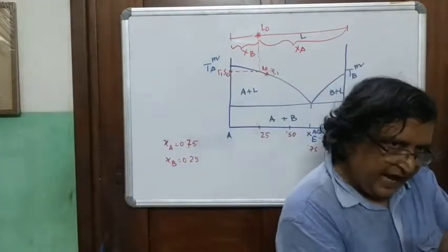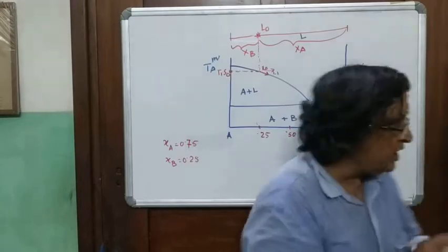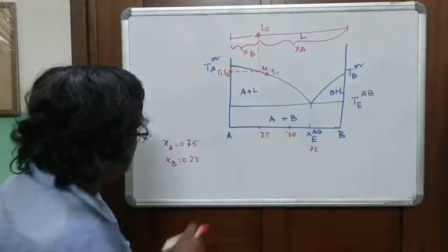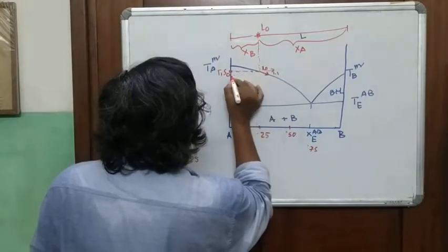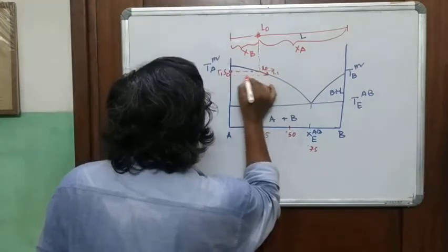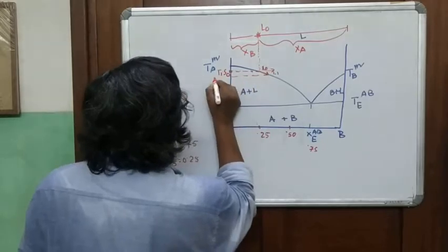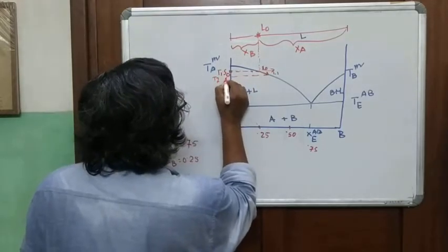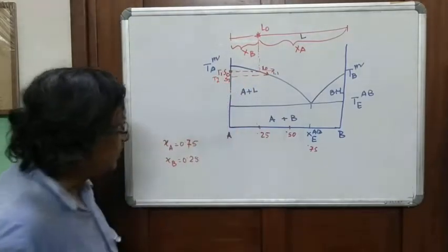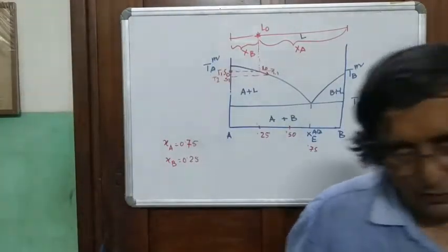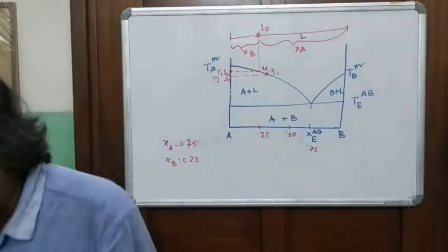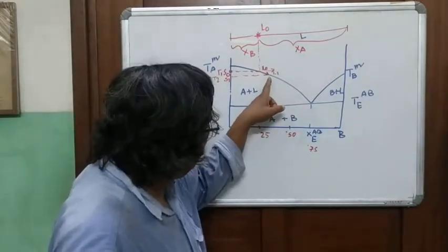A is now a crystal. The solid was S0 at L0, but at a lower temperature, T2, you will have solid S1, not S0, which is in equilibrium with the liquid L1.